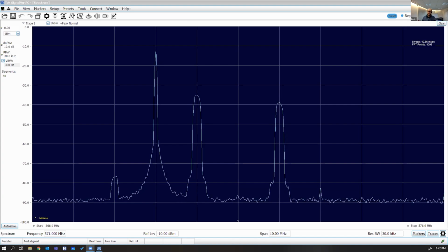If you have to use a mixed system between analog and digital, you have to use frequency coordination or banks and presets and apply it also to EWD. Or if you have enough space available, then just separate them. And as Greg already mentioned, for the equidistant spacing you just need to identify one spot in the spectrum which is empty, and you dump all your channels in there. It's really that simple. Okay, so let me stop this again.